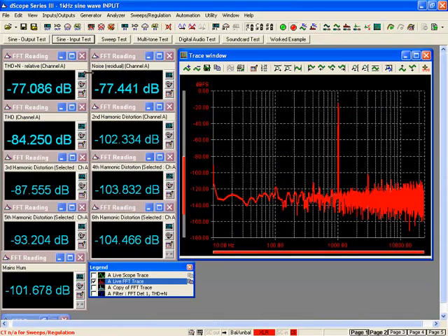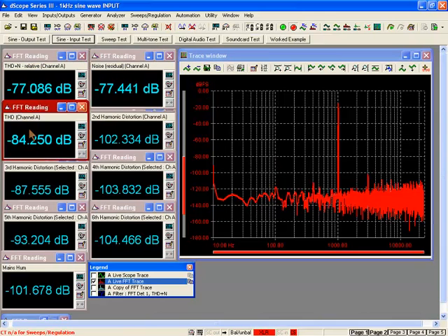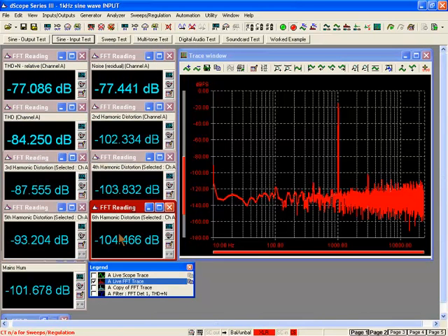And once again, we've broken that down into these numerical readings, which show you in very fine detail the performance of this device in terms of its distortion, its noise, its mains hum, etc. So that gives you a quick idea of how you would go about measuring your tablet or your other playback device inputs and outputs for a sinusoidal test signal.